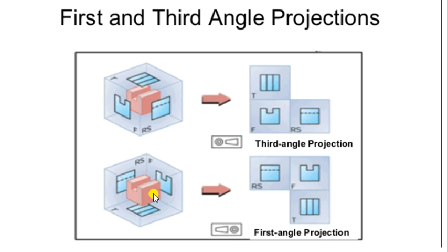Here you can see, and top view will be on the bottom side. Now we will rotate this top view in anti-clockwise direction, so that we will get it exactly below the front view. Here you can see in the figure at right bottom corner, like this every time we will do.